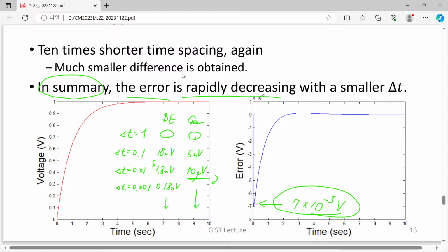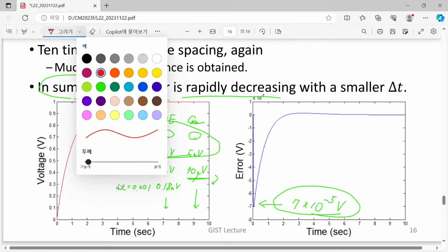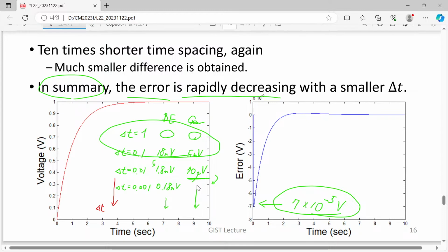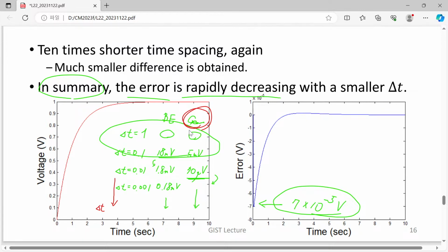So even though for larger values they show comparable behavior, if we go to a refined simulation with small delta t, then we can approach a much better result more quickly with Gear's second order method. So selecting a better method is quite beneficial for your accuracy.